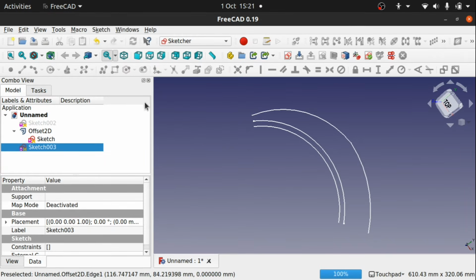So slots, polygons, squares, polyline, etc. When we come to the B-spline, it's a different matter, and problems can occur with that one if you want to edit it. So doing the offset and all that is absolutely fine. We can offset that, no problems at all. When we come to converting it bidirectionally between sketch and the actual wire there, then things tend to break down, and I can demonstrate that.